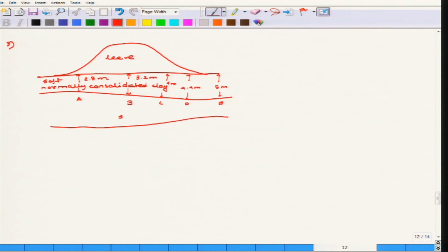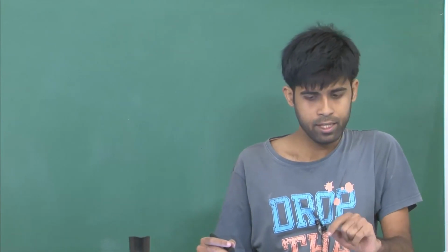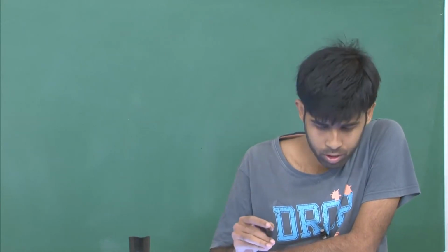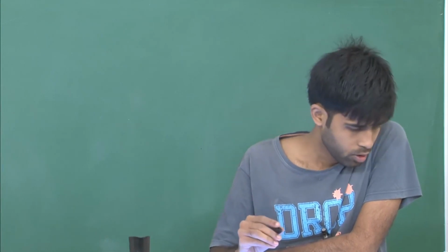Then there is a layer of sand and gravel, and there is an impervious stiff layer. Now, you see, in all the previous problems that we have discussed, we considered that the load imparted on the structure is actually constant, only the soil profile is varying. In this case, however, the levee itself is uneven, that means the load that is imparted on the soil due to the structure is non-uniform.